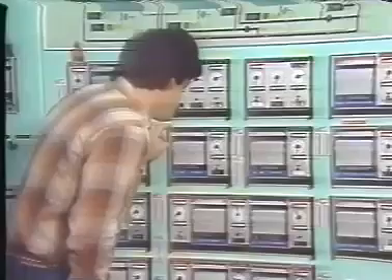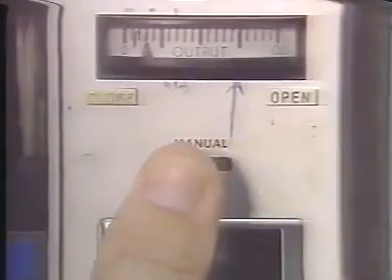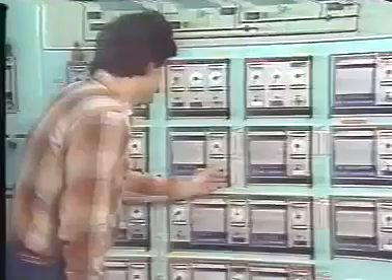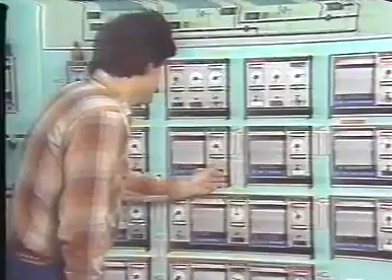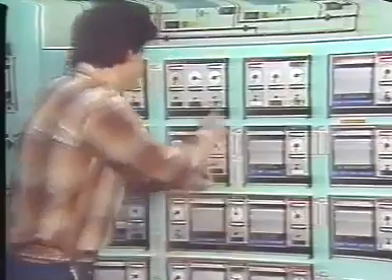In some instances, he may have to temporarily relax specifications on one product to avoid changing the composition of a more valuable product. During a process upset, it becomes especially difficult to maintain product specifications because an operator has to simultaneously make adjustments to several towers.